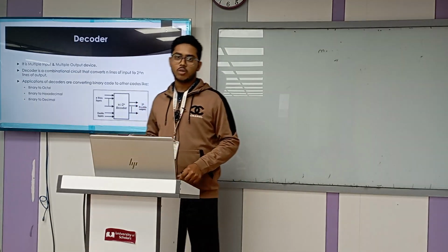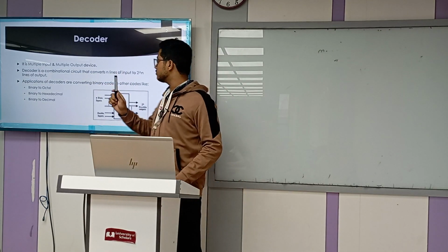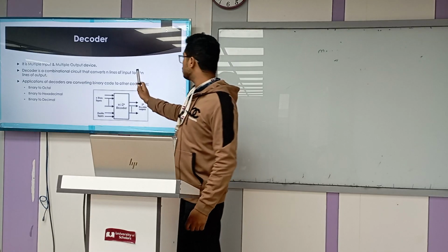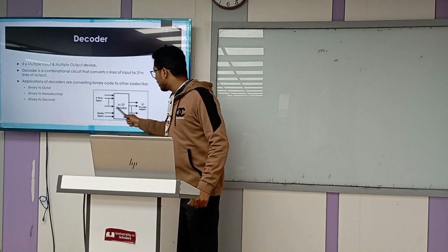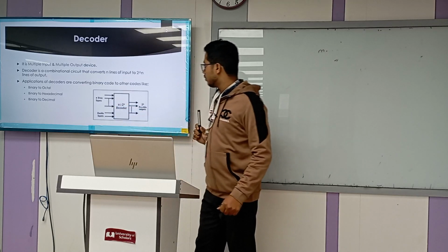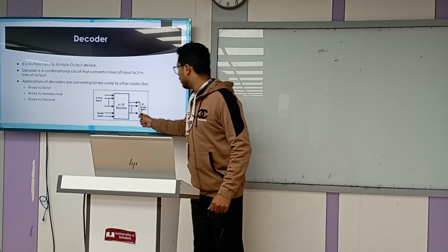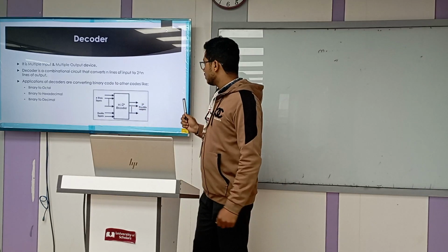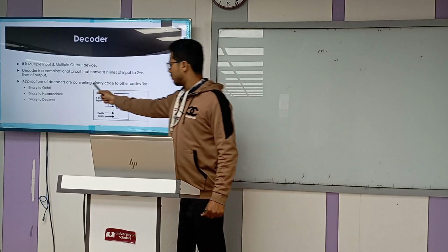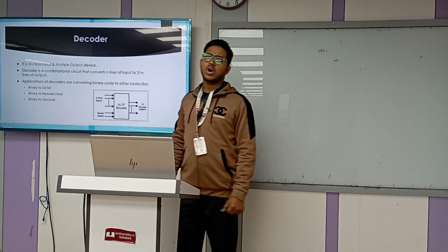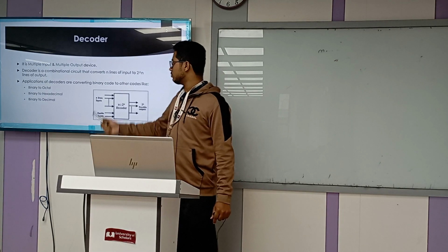It is a combination of circuits that converts n lines of input into 2 to the power n lines of output. Here you can see the block diagram. We input n data inputs and the output is 2 to the power n. Its applications include binary to octal, binary to hexadecimal and binary to decimal.